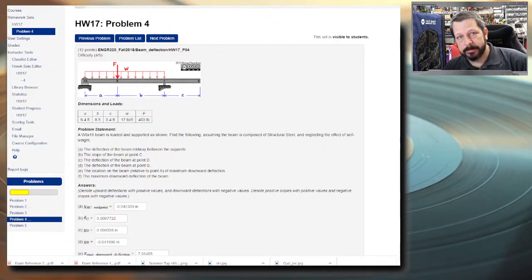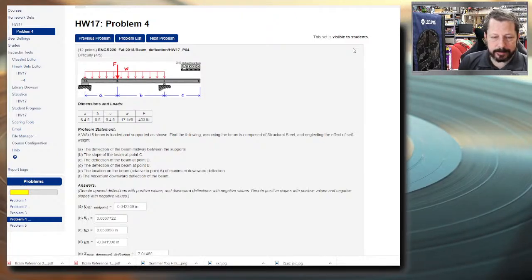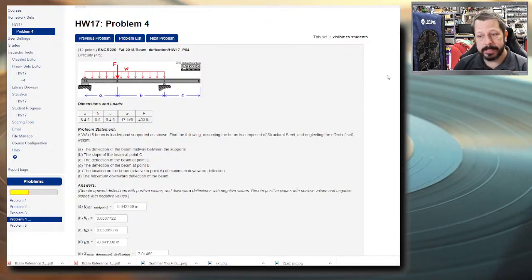All right. I will see y'all tomorrow. We'll do some SolidWorks. Oh, wait. I did get, remember last time we were doing SolidWorks beam deflection, I did get that to work. It was a really simple fix. I'll show that tomorrow also, because I don't have SolidWorks running right now, so it'd take a while for it to boot up. But it was a really simple fix. I basically added a rounded pin shape onto the end of the beam and constrained that as a pin, and it worked fine.